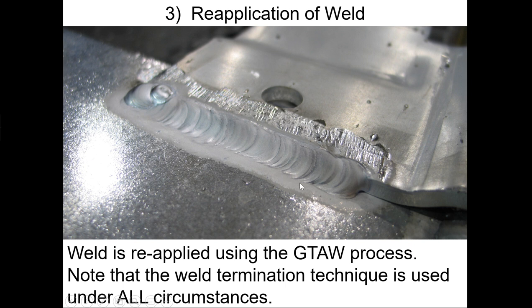See the cleanliness of the material? That's even going to show up in your technique. And then, of course, I terminated, and this is a hand termination, where I turned down the current and added filler material at the same time. After the weld, you know you're not going to be welding on it, you can take a soft disc. It's not a problem. You can clean this area up just a little bit, and it'll be fine.